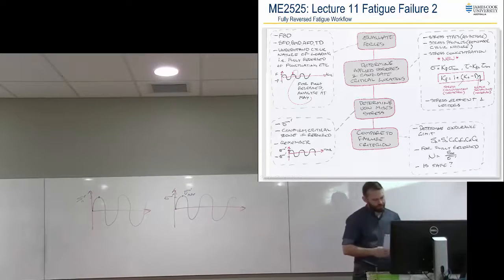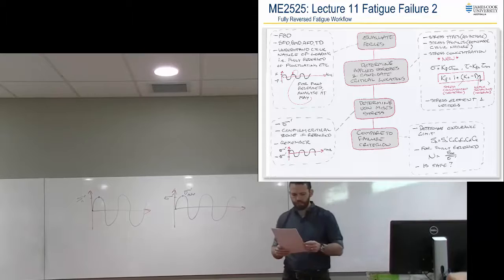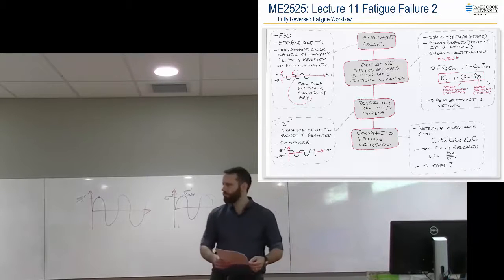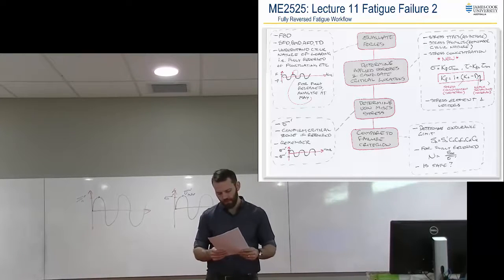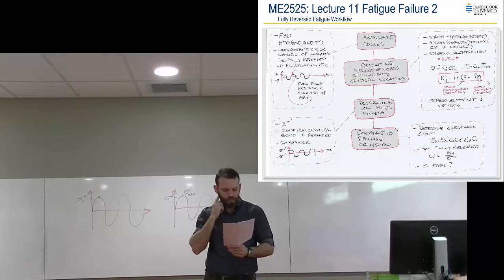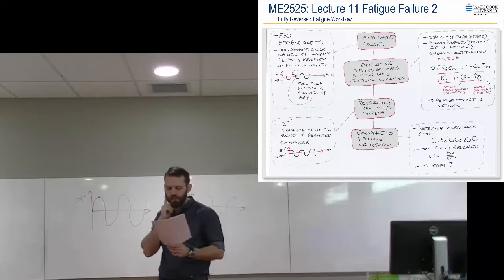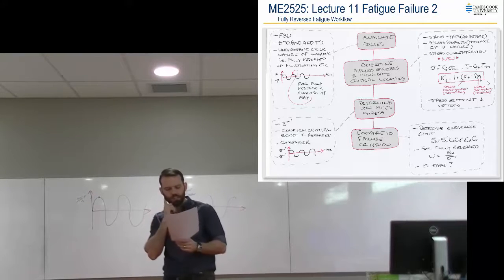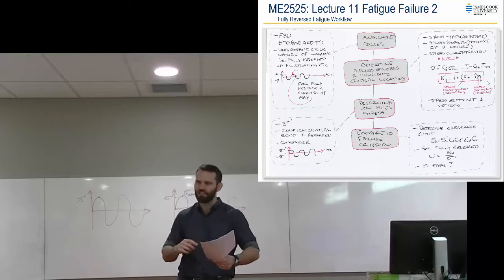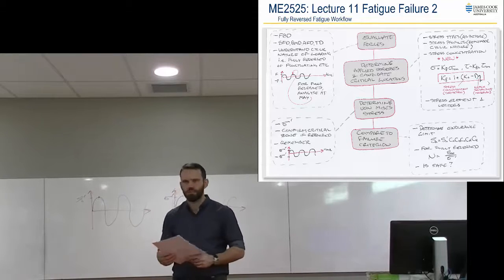And then so you read that off, and then off to the left you get a notch sensitivity that you throw into that equation. Cool? Easy enough, pretty straightforward. Over on the right there, a little bit more complicated. The bottom line's aluminium. The top one's quenched and drawn steels with Brinell hardness greater than 200, and the middle line is annealed steels with Brinell hardness less than 200. That's just the graph that we've been given.